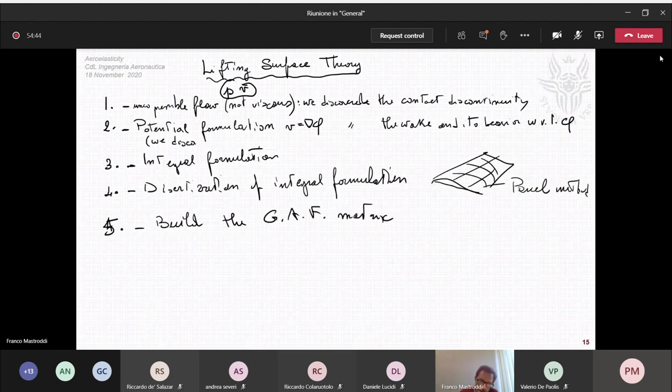So here we have coupled the potential flow theory issues with the structural dynamic issues, because now the body is moving, the aerodynamics is unsteady, and the pressures are unsteady pressures, and then we have unsteady aerodynamic forces, and these unsteady forces are exciting the structure itself, and we have closed the loop.